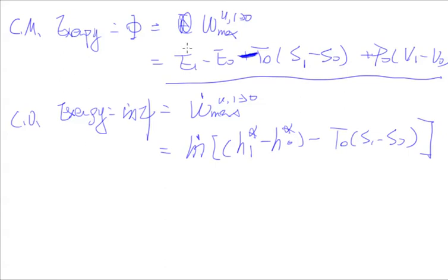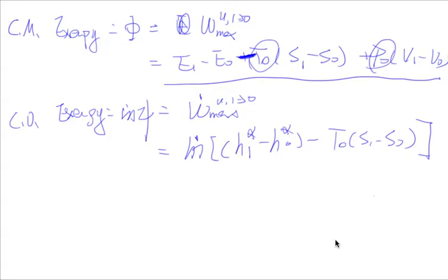Exergy is a measure of the ability to do work, the maximum amount of useful work we can extract from the system from a certain initial state, during the process of bringing it to the environmental state. It is a function of the initial state of the system itself and also the environmental variable T0. Exergy takes the unit of energy, but it's different from energy because it's not a conserved property.